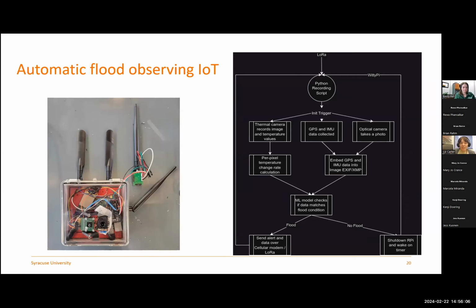All right. So that brings us to the project of interest. If we are going to talk about managing pluvial flooding in the same way that we manage our riverine flooding and our coastal flooding, what we need is some kind of a spatial estimate of pluvial flood risk. This allows us to prioritize maintenance and management of storm sewer networks and other types of flood control infrastructure in a way that is a little bit less ad hoc than responding to citizen reporting. And it also can help us to start to quantify the magnitude of this problem and integrate management of pluvial flooding into some kind of a federal regulatory framework.